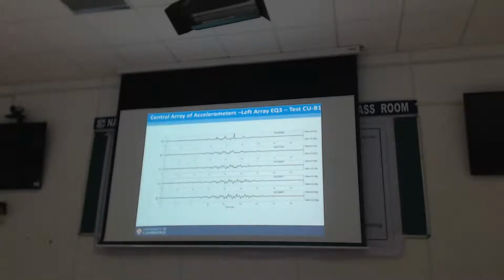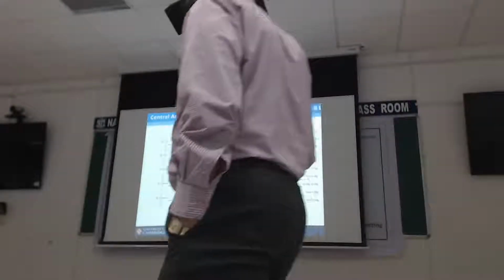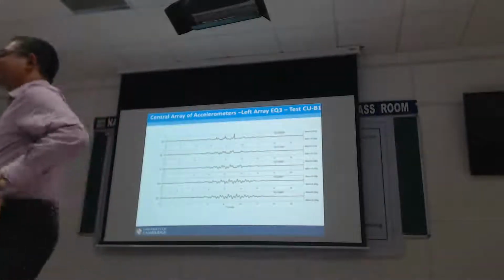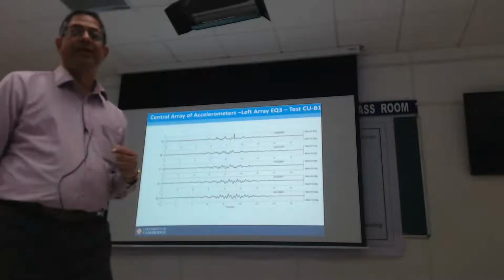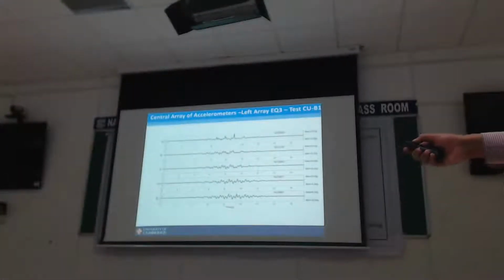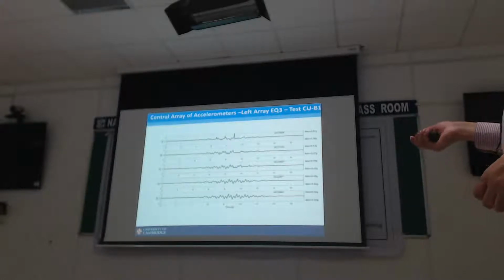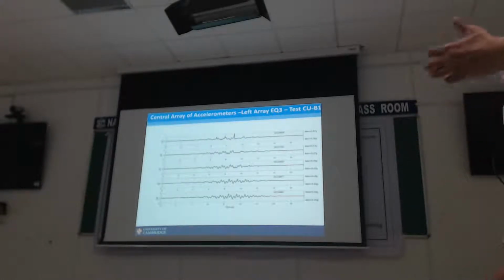And what does that tell you? That tells you that the soil at the surface, being under only 1 G condition, is going to be extremely dilated. It has no stress, so every grain can rise up as it wants to when you try to shear it. So your soil is going to behave in a very dilated fashion and lock up on you. Therefore, the accelerations can become really, really big.